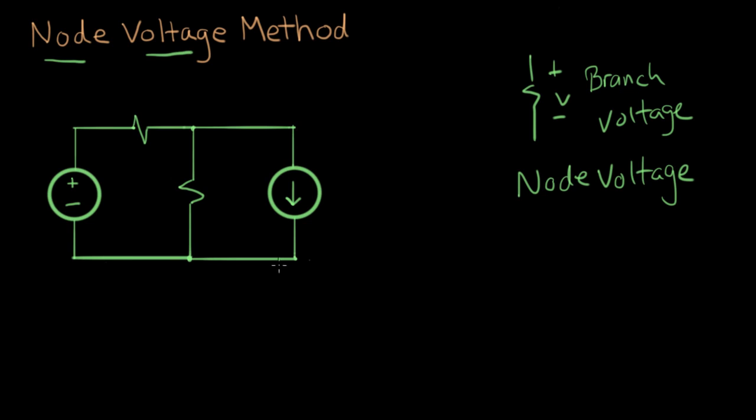It's not anything strange. But if we go over to our circuit here and we label the nodes, we'll call this node here, where this junction between this resistor and this source, node 1. This is the junction between these two components here. There's another node that's these two resistors connected to this current source, and that's a single distributed node. So we'll call that node 2. And down here, these three components are connected together in a junction, and that's node 3.